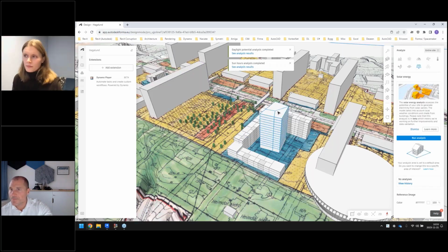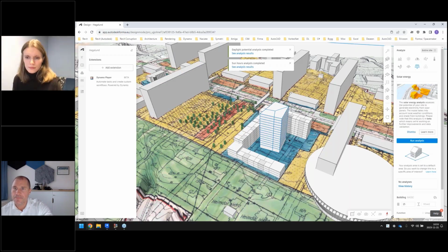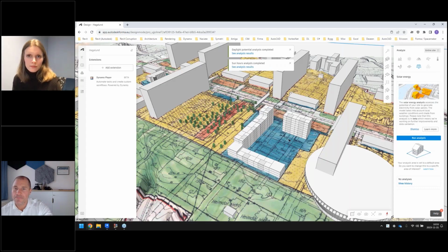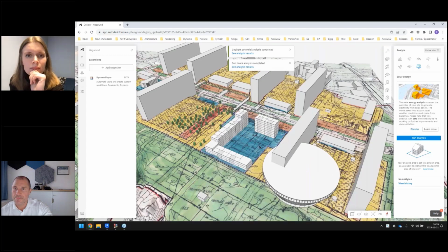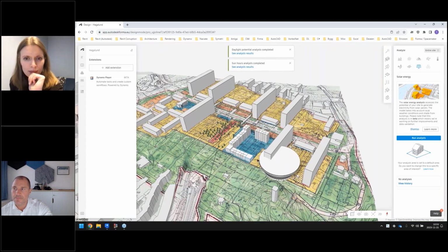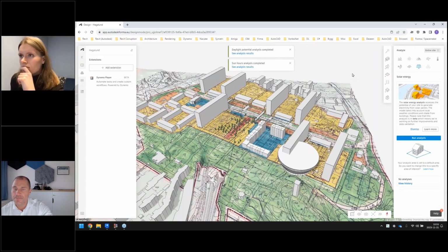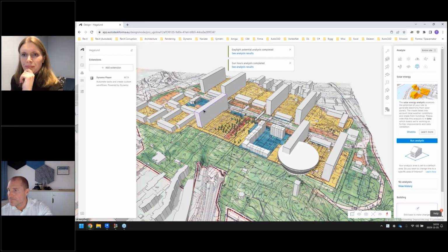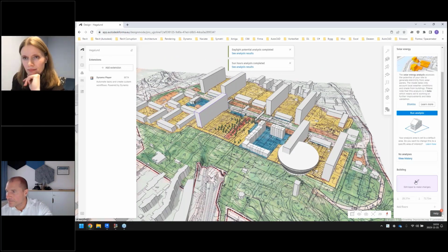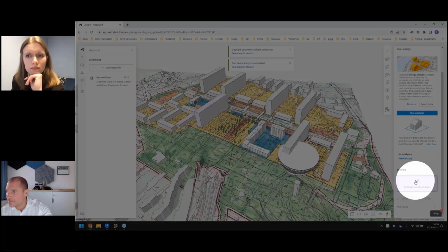Deleting volumes, I would delete them. I'm not sure, maybe you mean deleting from a part of a volume or something. If you mean deleting elements in the background, existing buildings, then simply select the building and try to delete it, and the function will tell you that you can't do it. You need to edit the base to delete the building.